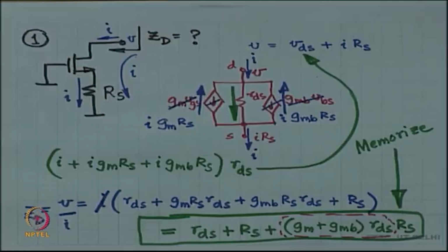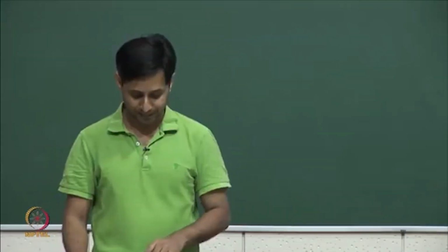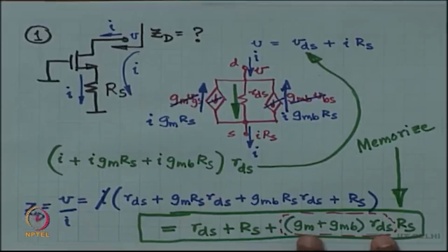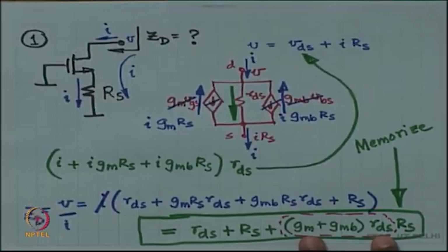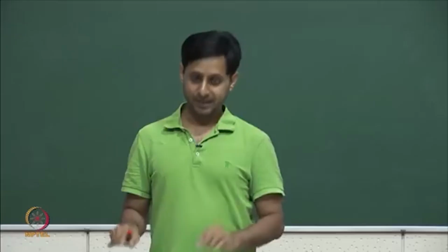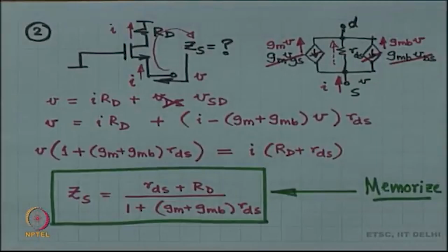Okay. Looking into the drain of the MOSFET, you see a high impedance, the impedance multiplies up. Okay. How much does it multiply? It multiplies up by a factor of the intrinsic gain of the MOSFET, right. This is a large number, I need you to understand this. Okay. While understanding, memorize.